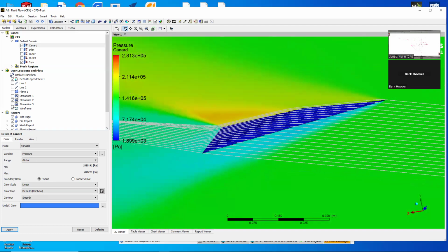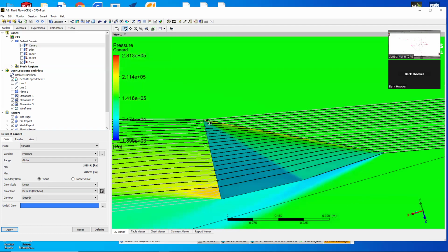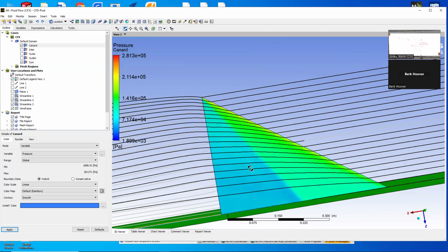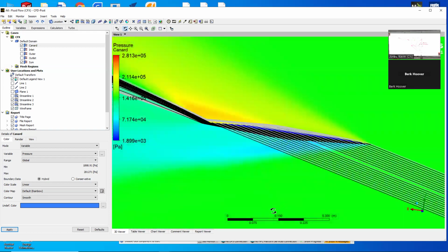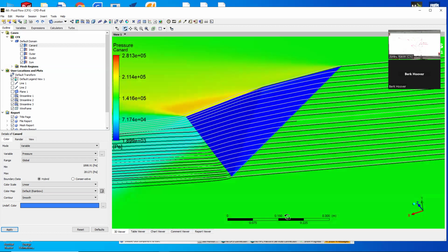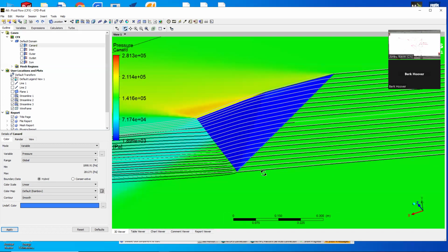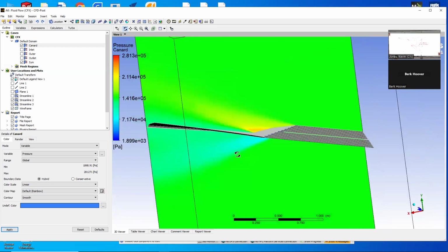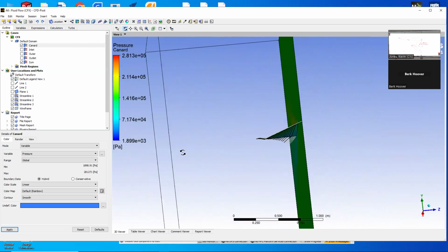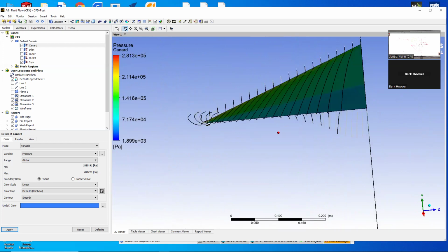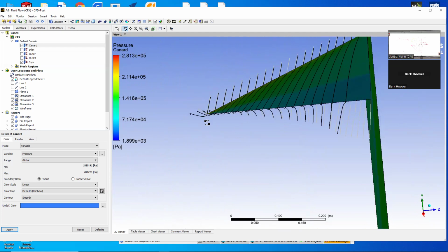I think I have streamlines on the bottom as well. And again, pretty benign. You can see a little more outward motion. You get away from the surface a little bit. Anyway, so that's highly swept wings: supersonic aircraft and missiles. That's why we do it. In this case, I maybe see a tiny bit of a tip vortex, not much.